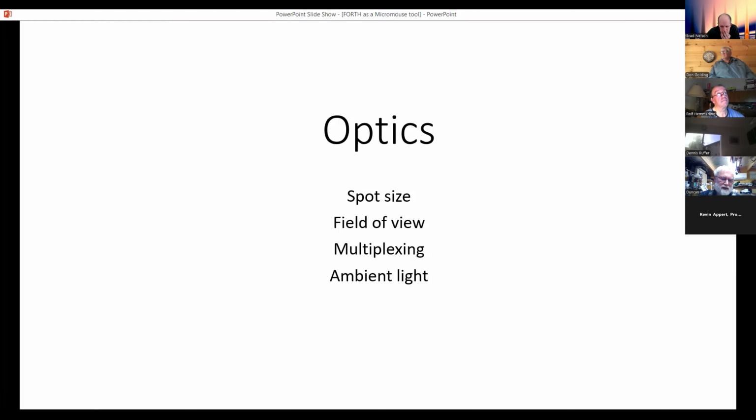You may not have enough ADC channels for your sensor array, so you might consider multiplexing one sensor between several LEDs. For example, the Raspberry Pi Pico, I think, has only got 3 usable ADC channels, so it gets a bit difficult to use that.